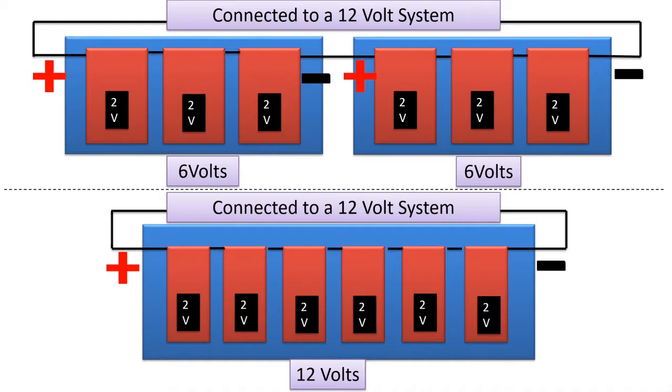A frequently asked question is which is better for RV use, 6 or 12-volt batteries? If we compare the single 12-volt battery with the two 6-volt battery configuration, a lot of this mystery can be simply explained. In either case, the charge controller or output devices see the configuration as a single 12-volt battery. The pictures clearly show that each configuration, at least electrically, consists of 6 2-volt cells wired in series that combine to equal 12 volts. There's simply not a lot of difference between the two.